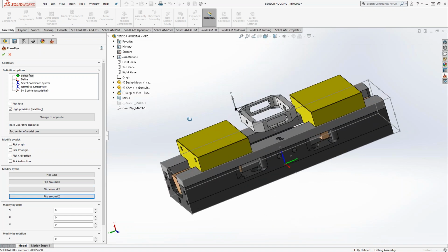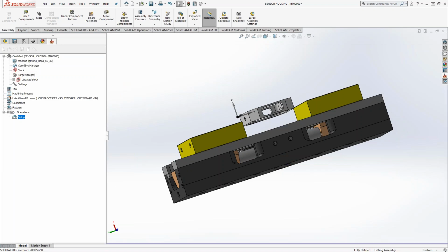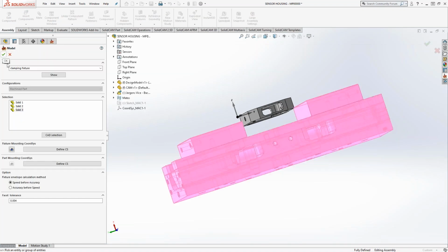So basically I'm just telling it that as this thing sits on the table, that's the reference point for when I want to shift it around. So if you have a machine sim, this is a really easy way to place the vise right on the table. You don't even have to figure out coordinates or anything like that. I'm going to get that to line up with the machine 0 just by saying the bottom center of the part is where I want that to sit on machine 0. Now, if it should be sitting a little higher up, or maybe whatever model you've selected is not the base of your vise, once you get to the machine setup window, you have that X, Y, Z coordinate to play with. And we're going to see that in a second here.